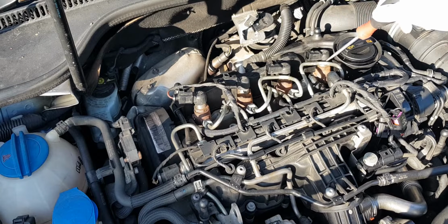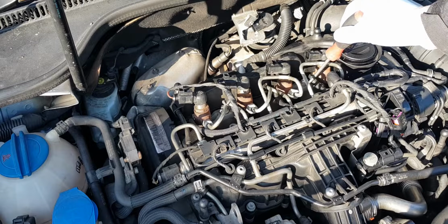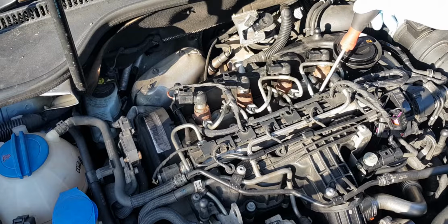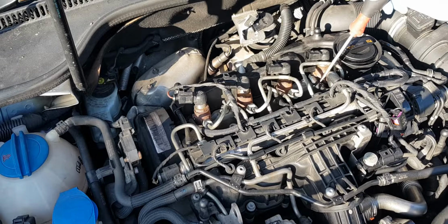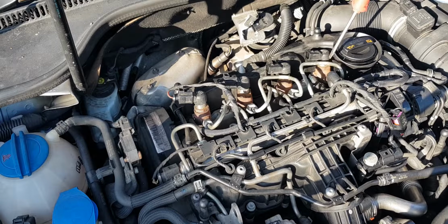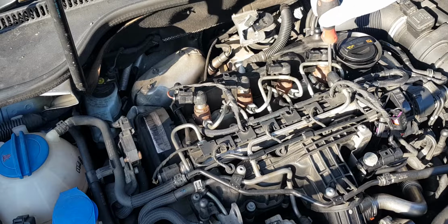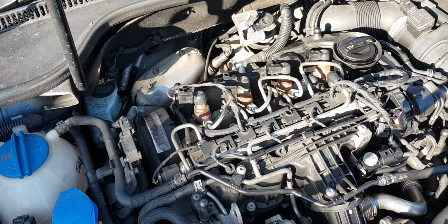In order to do that, obviously I will have to lift both, as they're held in place by this bracket here. So I'm gonna start by disconnecting the high pressure connectors here, the hoses, the high pressure pipes. And I have been told when I loosen these to then tighten it back here enough so I can wiggle the injector, and it will help obviously with the injector to pull out. Yeah, so I'm gonna start working now, and hope I help others with the same thing.